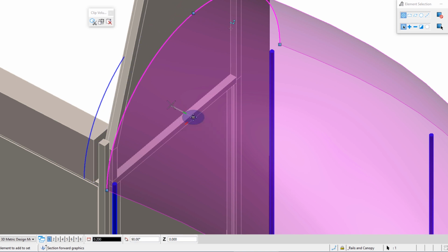Now what I want to do is I don't just want to move it out any distance. I want to move it till it becomes perpendicular to or parallel, depending on how you look at it, to that building. So if I just move my cursor along the edge of the building here, it's basically going to snap to these points, and that's not what I want. I want to lock myself on this axis. So I'm going to do this by, it's an AccuDraw shortcut, pressing Enter on my keyboard. We call this Smart Lock.